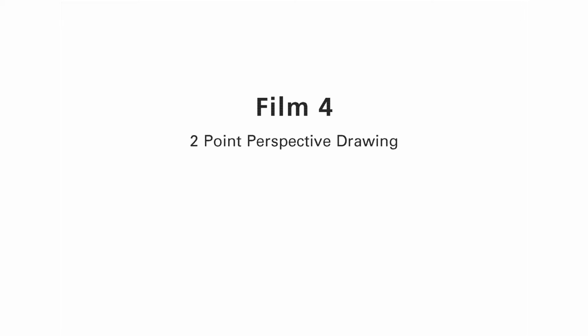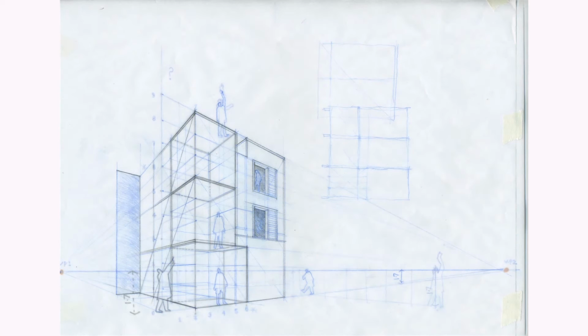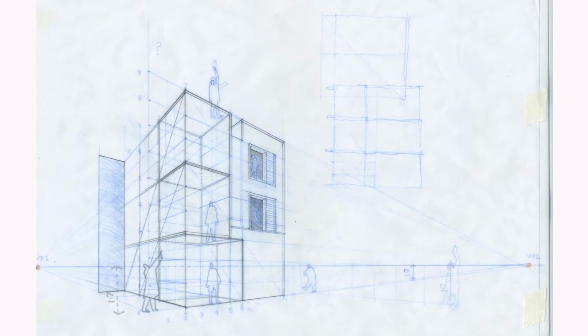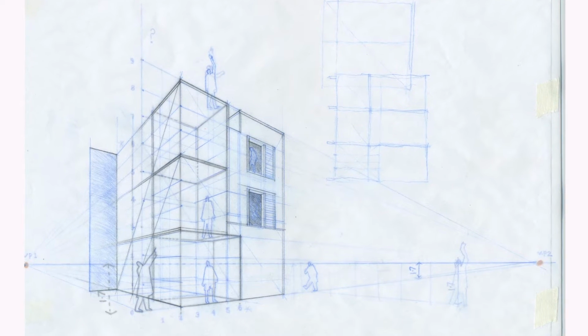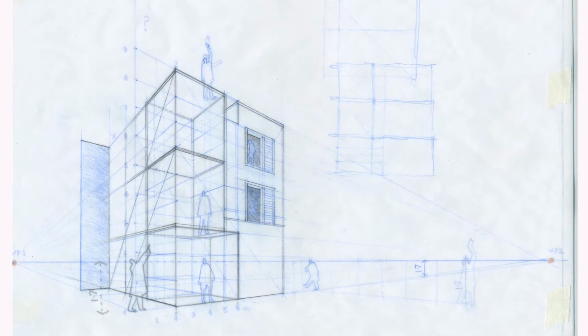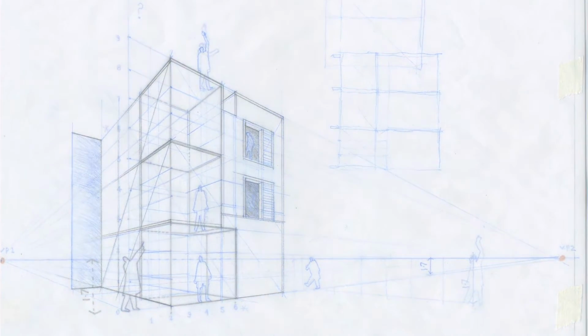Perspective drawings show the way your designs will look in real life. They are useful for communicating with a client who may not understand technical drawings. Most commonly used is the two-point perspective, and in this film we are going to construct a set of perspective grids that enable you to draw shapes receding and advancing from vanishing points.